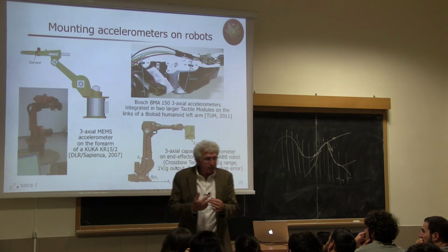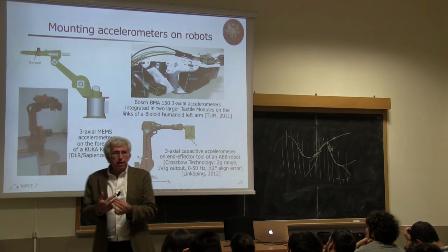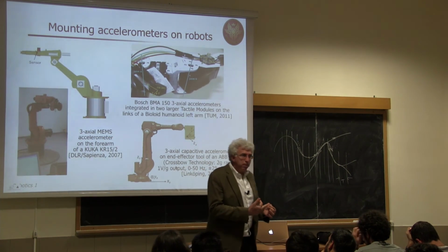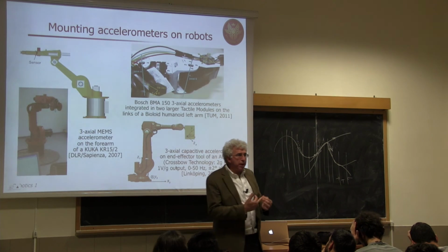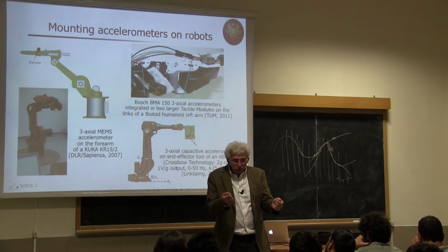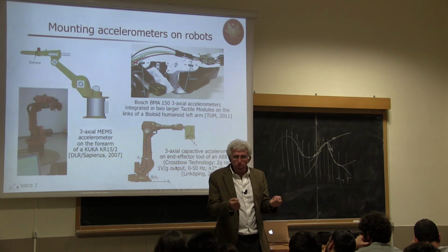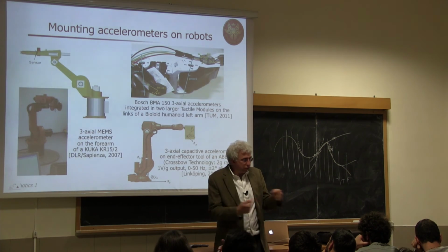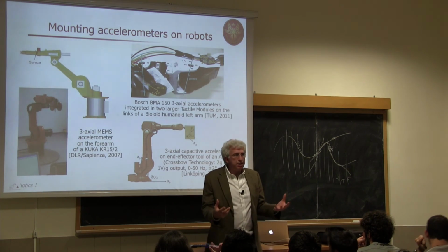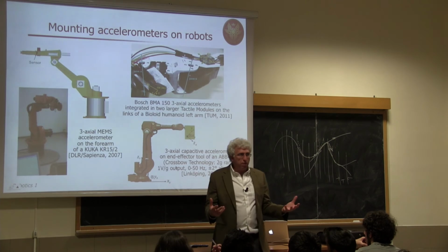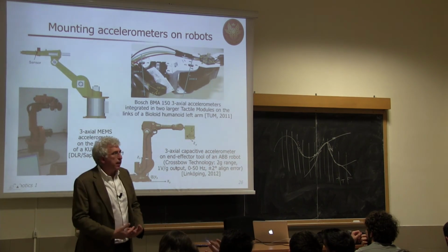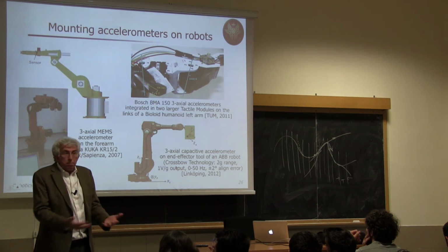Okay, so pay attention to this, because otherwise you would run into a non-causal problem, a so-called algebraic control loop, when you're trying to control your system using a measurement which depends on the control that you're applying. So you don't know which comes first, and you have a loop. And this is really sensitive to instability problems. If you have elasticity, then the accelerometer can be used to measure part of the state.